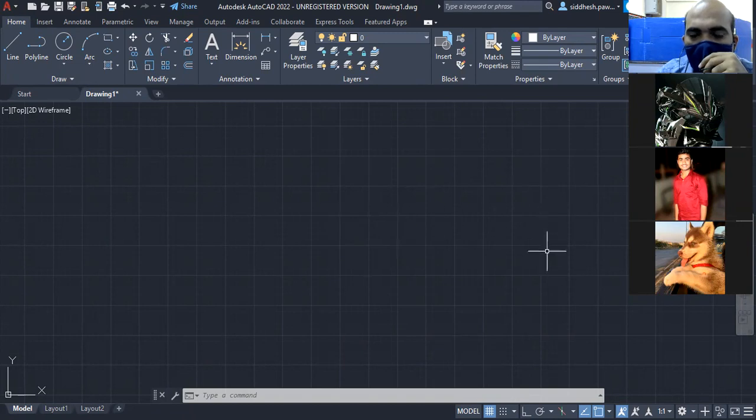And what we have done right now, you are supposed to do every time. Whenever you are opening AutoCAD, you have to do it, so that at the starting of the session you are very clear that you have to finalize your limit size as well as dimension both. Okay. Now what we will do is understand how to make a line.